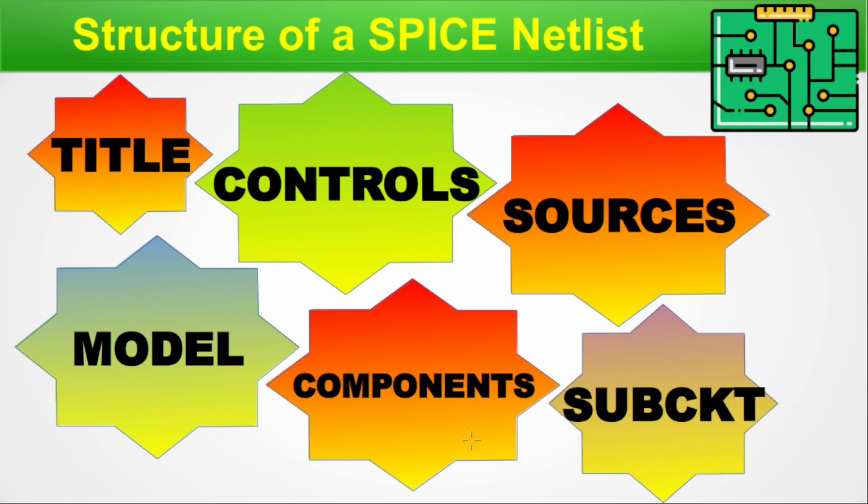Now, some of the components may not be sufficient to operate with the models. In those cases, a subcircuit will be there. A subcircuit is a compact version of the component and the model for a particular block, and that block has some individuality as its input and output. So, those subcircuits will be used. In industry, this kind of subcircuit may come from the foundry, or it can be internal to the IP team. The IP team may give you the subcircuit and you can directly use it, or it may come along with your foundry PDK.